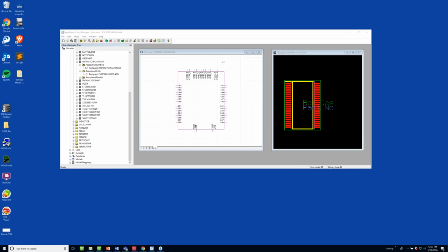I'll jump into the creation of the schematic. The schematic I'm about to show you fits into this larger ventilator design. When you start a schematic, the first place you need to look is the creation of a library. Every schematic, you place down components, and those components typically have a logical definition, which is this symbol here, and then a physical representation, which is a cell or footprint.